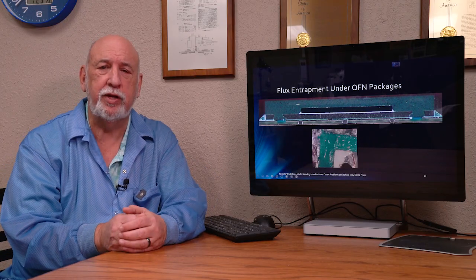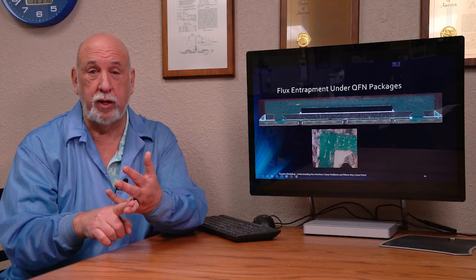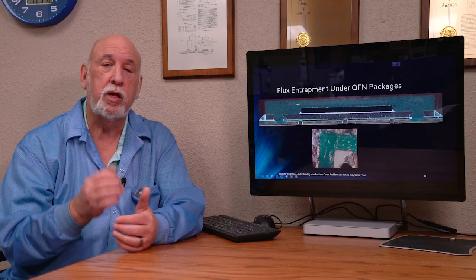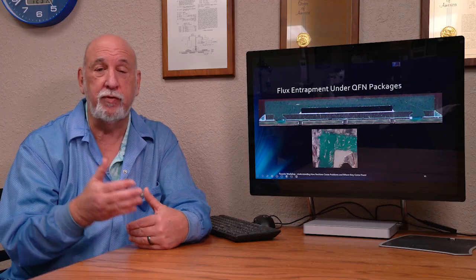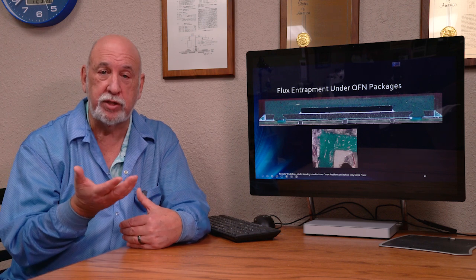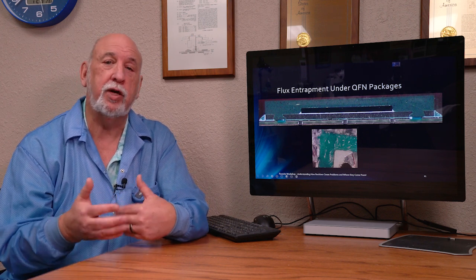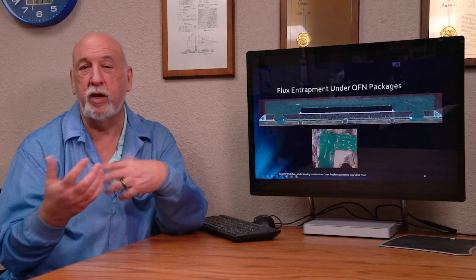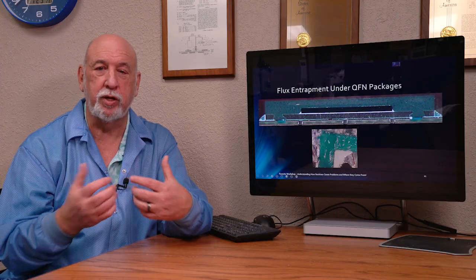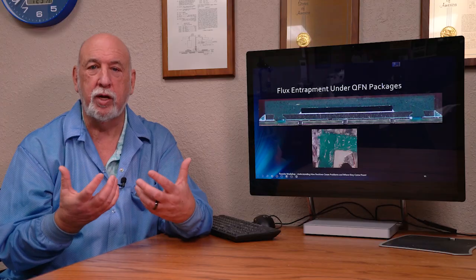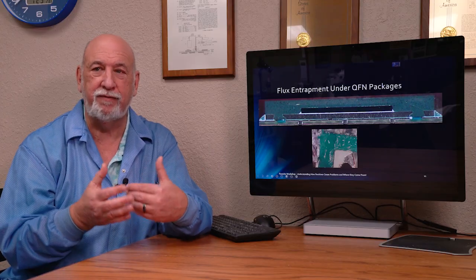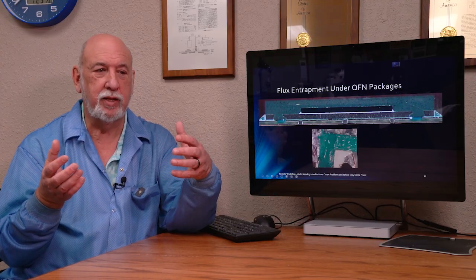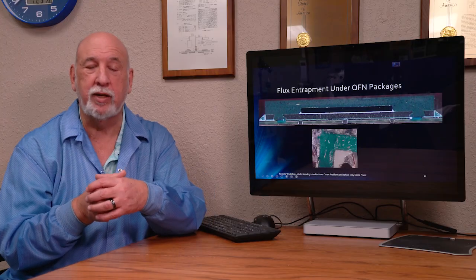And it makes it very difficult to A, clean, or B, let the flux properly vent. We found that between 3.5 to 4 mils, if you've got a good standoff, that will give you much better venting performance and be able to create a much cleaner condition in which the effect is less impacting.